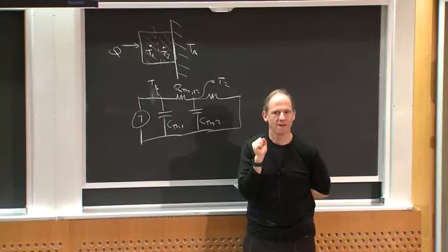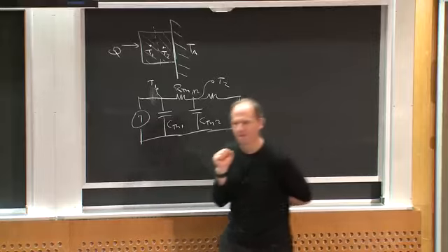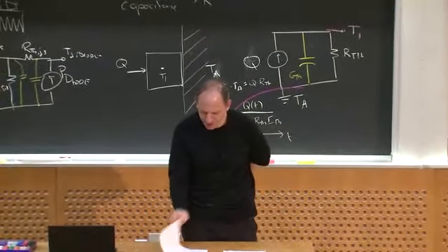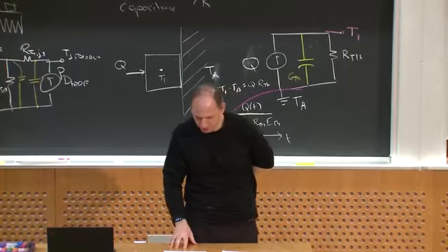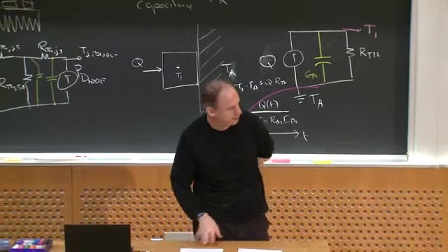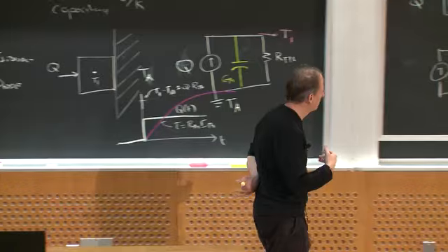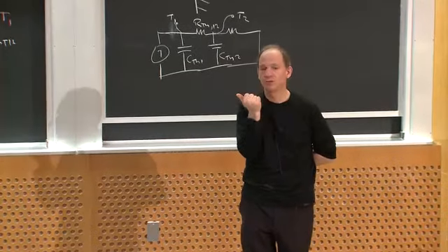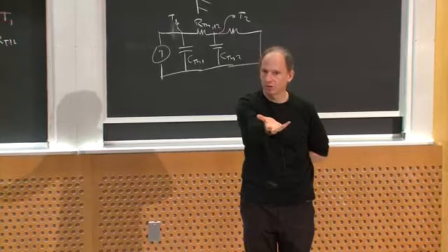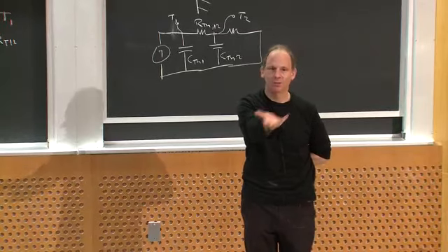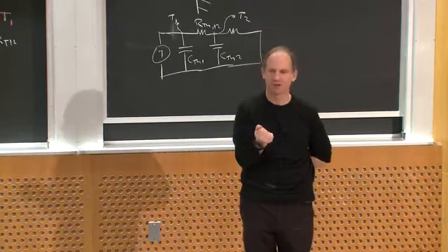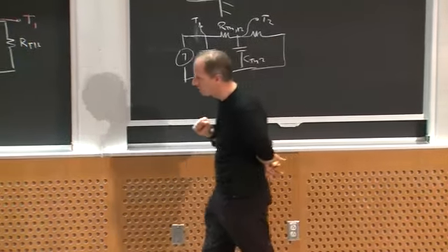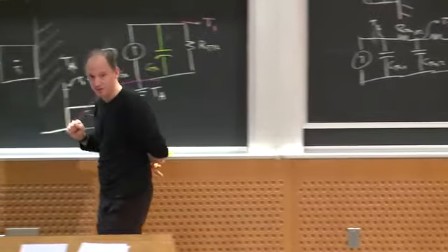Any other questions? Okay. How do people model the thermal capacitance aspect? Sometimes if you have a material, you can go look up its heat capacity and then multiply by the mass, and you get a thermal capacitance, and you can do it from fundamentals this way. That's not always the way they give it to you for a device.